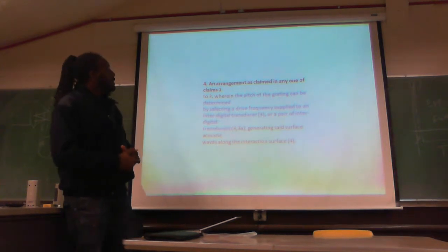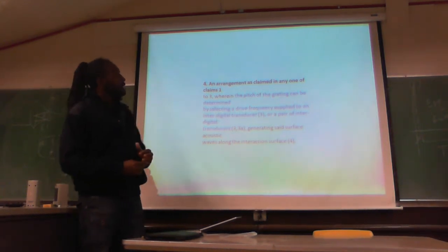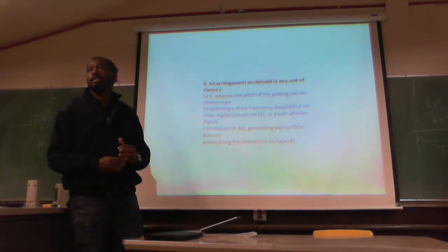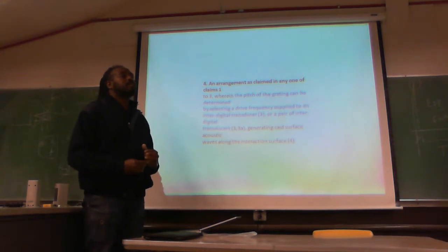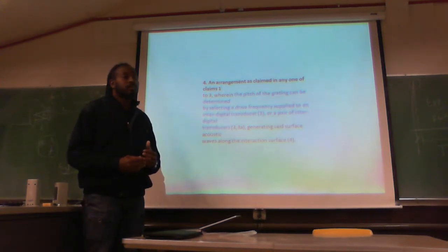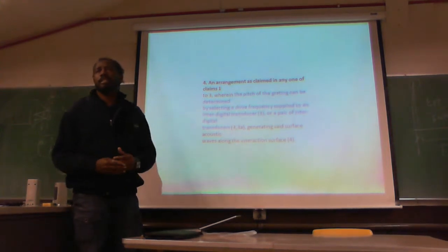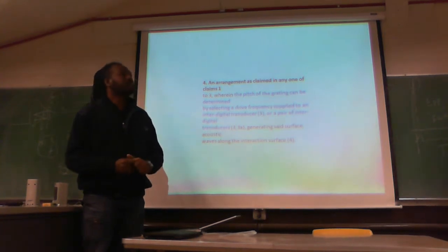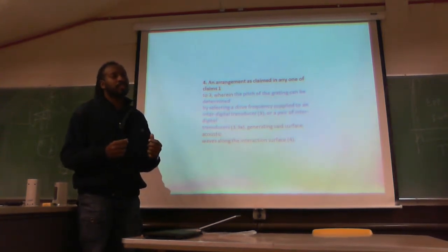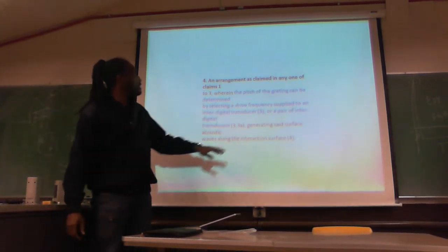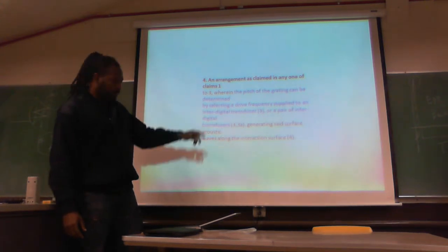As far as a pair of interdigital transducers in laser ultrasonic UT or ultrasonic testing, sometimes one transducer is used. 5 megahertz for aluminum, 1 megahertz for coarse steel. For deeper penetration, usually 1 megahertz. Wider penetration, 10 megahertz. For 2 transducers, they use the pitch catch method. So that's one instance of using 2 transducers.